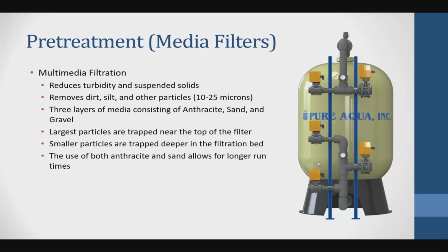The second cycle is when there is a backwash, this valve is going to be closed. That's the inlet water for the backwash. The reason why we have a separate valve is you can use the same city water or the same as the feed water, or if you want to use a separate filtered water. So you can have a different source of water to backwash the filter.